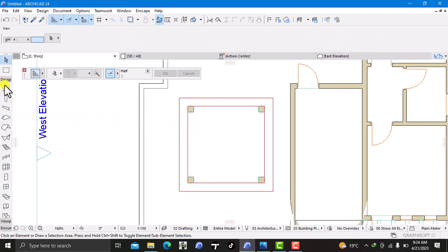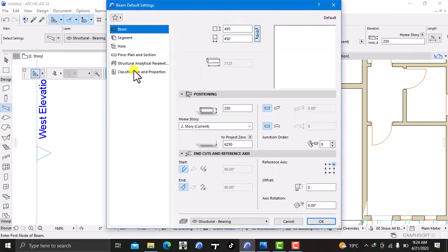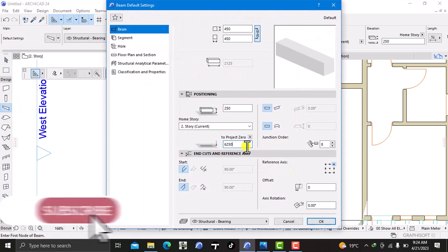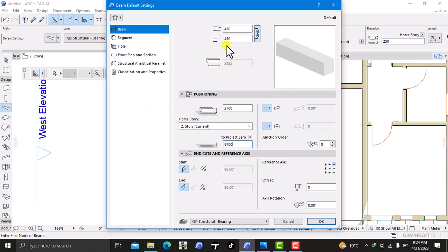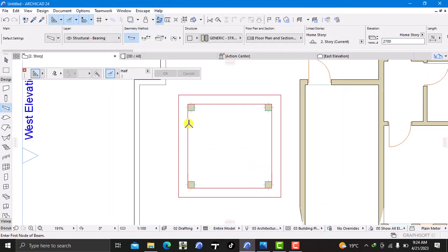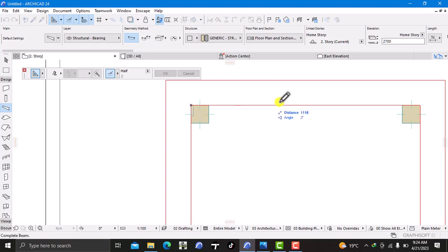Since I'm going to use some beam tools, I'll go to my beam tool, set it to project. So 6000 plus 2700. 6000 plus 2700 gives me 8700. So 8700. That's that, and then I can use it. Distance of walling of 150. The thickness of the beam I can work with 150 by 150. Yeah, to project. Yeah, and my reference can work with that. Shift that, and then just go from this edge to this edge.